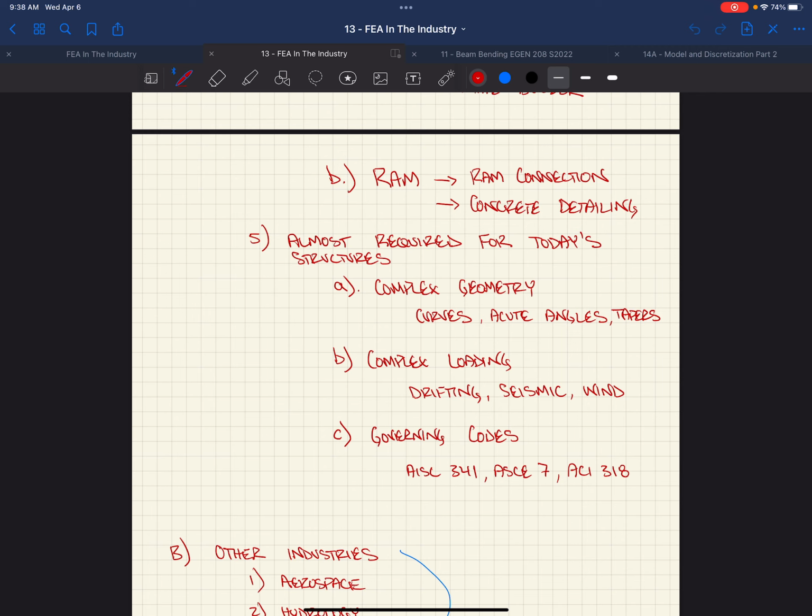Or one of the biggest concepts, and I'm gonna try and instill this into you guys, is when you're designing special concentric brace frames, Damon has told you, right, the brace is the fuse, right? The brace is the fuse. It's supposed to turn into a piece of spaghetti. We're gonna stretch that steel till it yields, right? Then we're gonna turn around and push it until it buckles. We're gonna do that multiple times. And that thing, right, the fact that that thing is stretching and buckling is the whole premise behind the fact